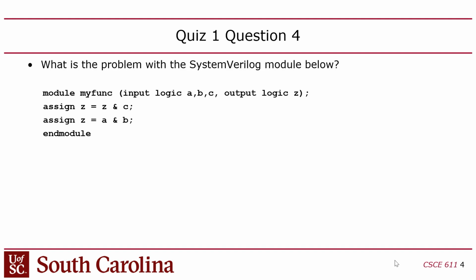So there was a fixed iteration limit. It would limit the number of triggers per time step. You advance the simulator, and if there were more than, say, 10,000 triggers, it would just bail out. But when we switched this class to Verilog, for whatever reason, it quit doing that, and it just went into an infinite loop. There's probably a hidden option in there somewhere that you can use to set the iteration limit, but by default for Verilog, there's no iteration limit. And even if you get the iteration limit, it doesn't tell you where the loop is in your code.